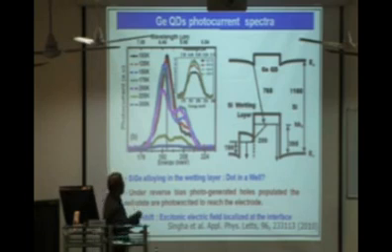In fact, this is the band energy diagram. When I was talking about the photoluminescence, I was saying that one hole is confined here and the electron is localized here. So there is a strong overlap of the wave functions that gives rise to emission. In the case of the photodetector, the hole is localized in the valence band of the germanium. So basically they are first excited to, there's one more layer in this case. I will not go into the details, this is a little bit of the growth.